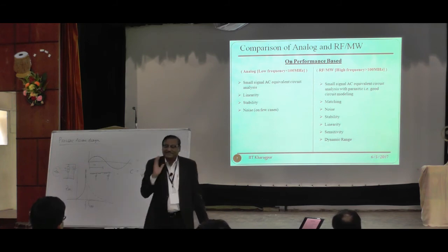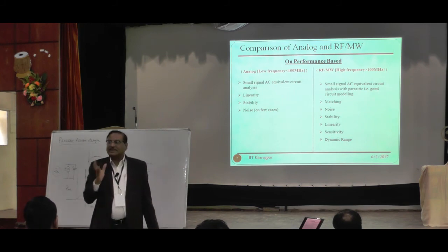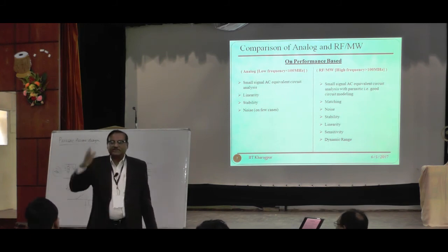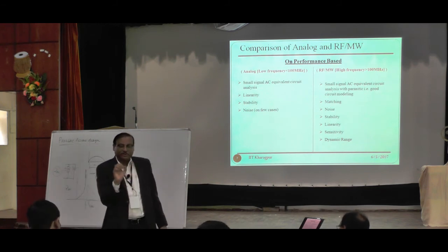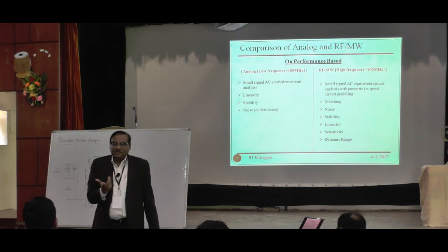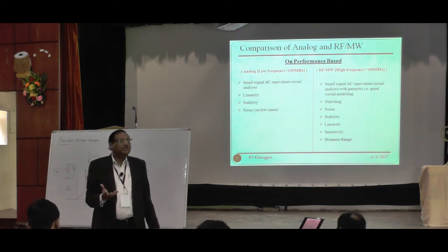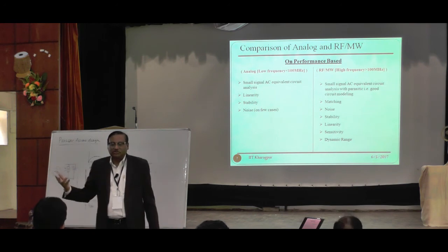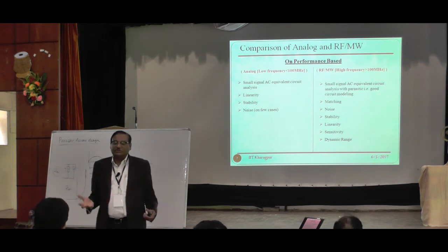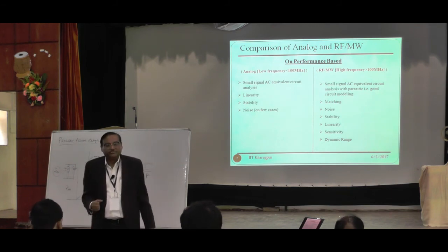But all of you know that any semiconductor is nonlinear in nature. The IV characteristic itself is an exponential characteristic. And if it is exponential, and I am giving an input periodic signal, definitely it will give a nonlinear output. And nonlinear output introduces what? Harmonics. So for 2.4 I will get 4.8, and all those second, third, fourth, fifth harmonics. And those harmonics introduce distortion in your output signals.